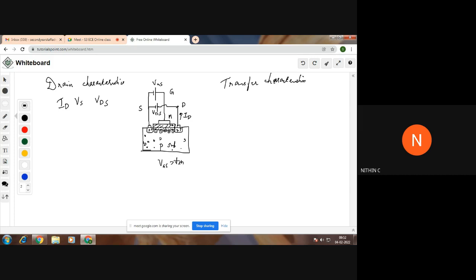So ഈ VTH മുകളിലേക്ക് നമ്മൾ VGS ചേഞ്ച് ചെയ്യുന്നതിന് മുമ്പ് മൂന്ന് കാര്യങ്ങൾ അവിടെ നടക്കുന്നുണ്ട്. VGS less than 0 ആണെങ്കിൽ there will be holes, there is no channel. VGS slightly positive ആണെങ്കിൽ you will be having a layer of negative immobile ions. കുറെ immobile ions ഉണ്ടാവും, അത് depletion ലെയറിന്റെ ഭാഗമായിട്ട്. So then also we are not having a channel. The channel is formed only when VGS is raised above VTH. Okay, clear?